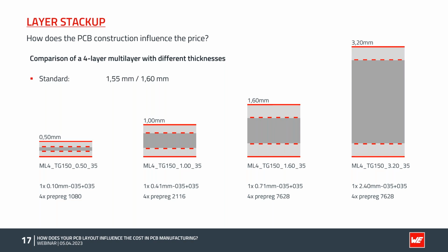So what is the difference here overall? We change the thickness of the dielectric of the core which we are using, and we are changing the prepreg styles. The thinner the glass gets, the harder it is to handle for the manufacturer of the FR4 material. So a 1080 prepreg or a 106 prepreg, well, they have to run their processes just slower because the risk of breaking the glass cloth during the impregnation is just higher. So that's the reason why when you compare the cost and you say 1.6 millimeter, the standard would be 100%,